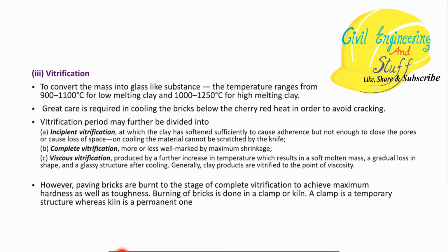The chemical constituents that were earlier bonding together to impart hardness and strength to the brick will now start to melt, and the brick that we get once it undergoes viscous vitrification will be of poor quality. It will exhibit a crystalline or glassy texture, and upon a small action of load, it will break.